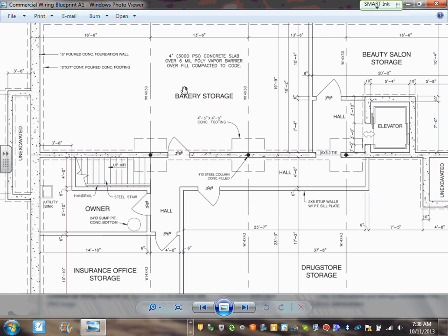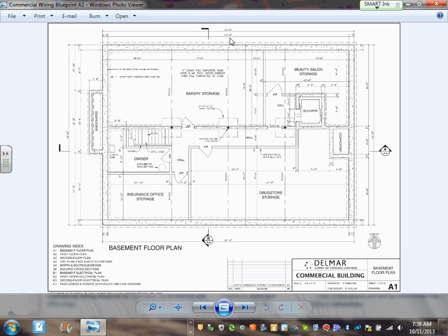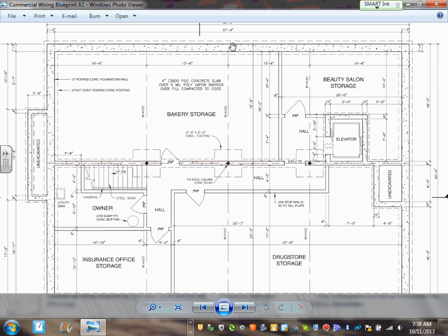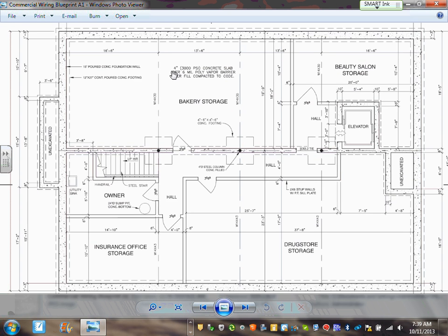So when they ask you to refer to the blueprints from this book, they're asking about these blueprints at the back of the book. Everybody understand that one? So I'm not going to go through the architectural one. Why do we like architectural stuff, guys? The good thing about the architectural blueprints is that they give you more details about the type of the building. Is it type 1, type 2, type 3, type 4, or type 5? Based on the type of the building, Brian, you can use certain wiring methods, and you shall not use other types of wiring methods.